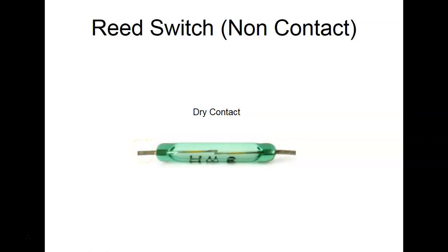You usually can't actually see the switch. It's usually incorporated in some plastic, but it'll only have two leads coming out of it. So this would be a 2-wire sensor. And I thought I had one over here, but in reality I don't. These are the switches right here, and they're really, really close. So these guys couldn't handle a lot of current or high voltage.